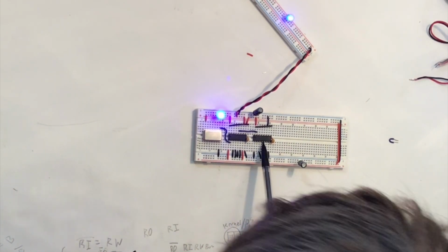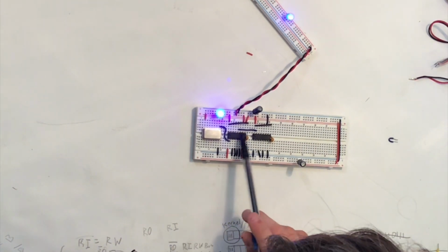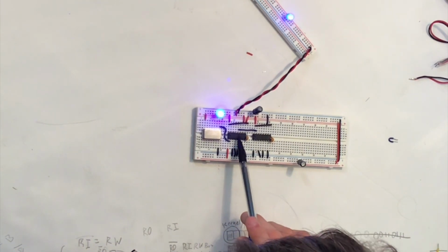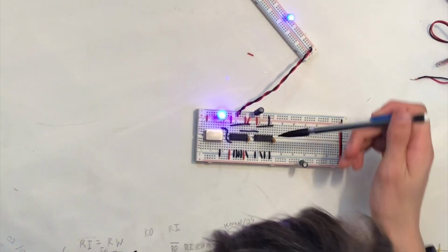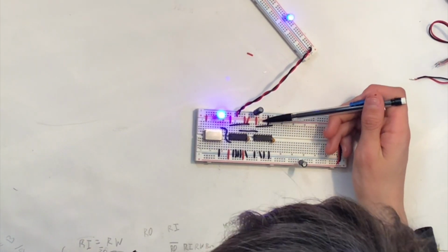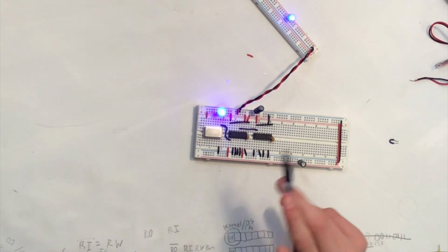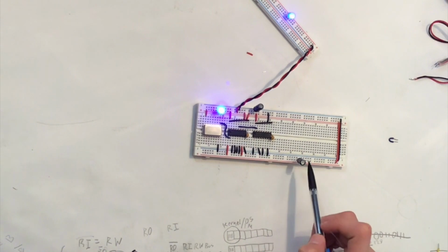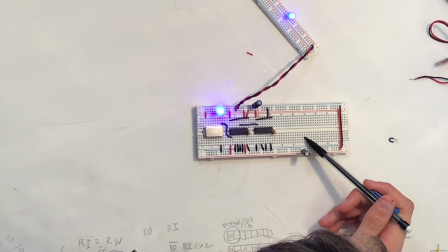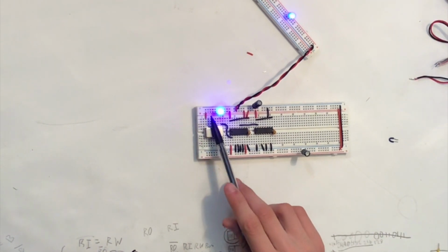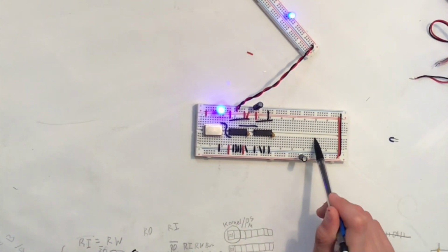Then this is the inverter I use to get the not clock. I just invert the 2.5 megahertz. That's the inverter used to do that. It's really not used for anything else here. I should tie that line low as well to prevent noise on the chip. So that's the main circuit. I have bigger decoupling caps for the board, an LED, just more of an indicator light. It's a pretty simple circuit, but it gets the job done.